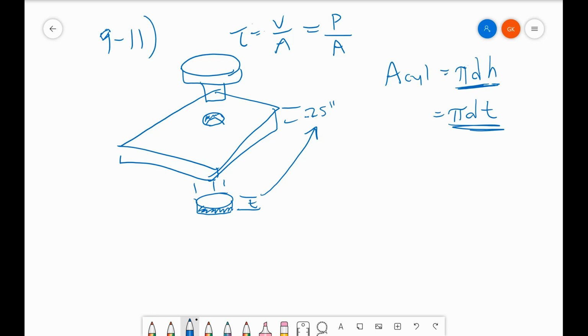so with that in mind, let's try some stuff. Or not. Now, you're watching a video. You can do what you want. So first off, we have our shear stress equation. It gives us a couple more things. First off, it says the punching operation is going to be with a diameter of 3/4 inches. So given that this diameter right here is 0.75 inches. So D equals 0.75 inches.